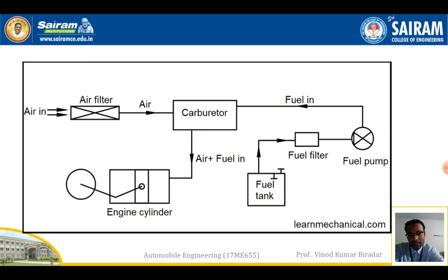In the engine cylinder, combustion normally takes place. A spark plug is connected in the engine cylinder. When the fuel enters the engine cylinder, four strokes take place: suction, compression, power and exhaust. Suction means it will suck in the air-fuel mixture, compression means it will compress and increase the pressure and temperature, and then the power stroke does the work.